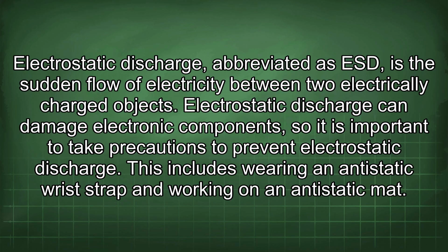Electrostatic discharge, abbreviated as ESD, is the sudden flow of electricity between two electrically charged objects. Electrostatic discharge can damage electronic components, so it is important to take precautions to prevent electrostatic discharge. This includes wearing an anti-static wrist strap and working on an anti-static mat.